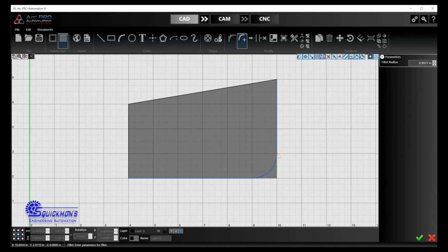It'd be more cosmetic especially if you're trying to repeat the same length or the same radius on a fillet. Notice up here wherever I drop that, it has this really random number up at my fillet radius. So on most parts you're going to want to give it a call out and be consistent across those different radiuses. That's just normal practice. So you might want to run like an 1/8 inch radius or a 60th thou radius, 16th of an inch. So you can really utilize those two commands, the fillet as well as the chamfer tool, and get creative with those parts. Once you click check, there it is.